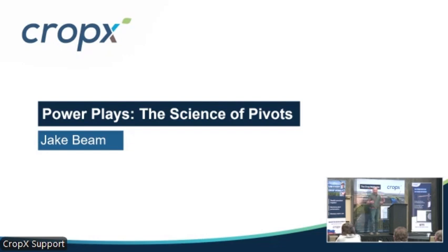we all take terms for granted, right? That everybody should know what we're talking about. Number one that I think about that we all take for granted is ET, what it is, and how we account for it. So part of this, I'll even throw in there how we can design pivots based off of ET demand. So, and how we measure some of that water.